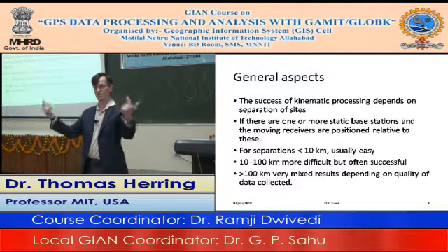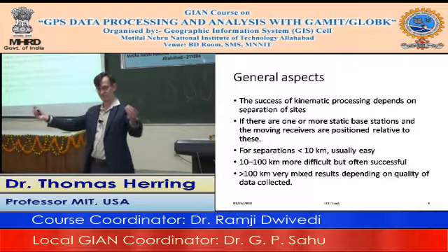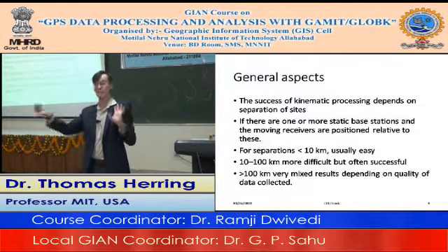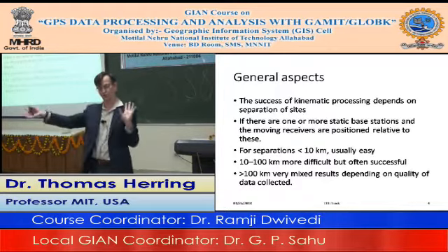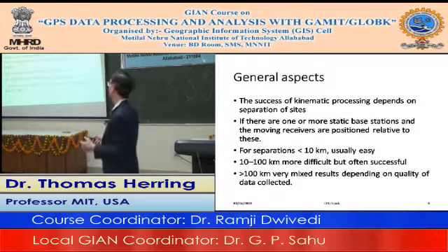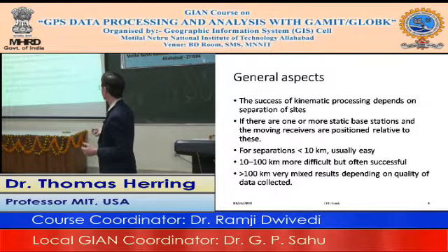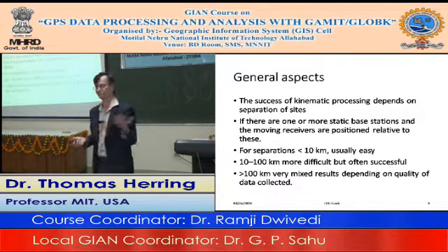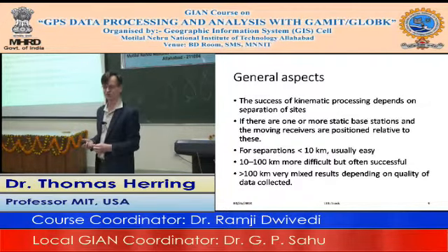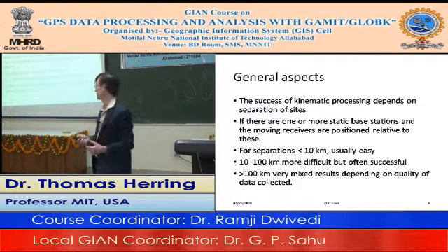So we could actually keep, when you go very far apart, you have a problem that the satellites that you can see from one receiver to another receiver are different. And so if you get too far away from your base station, you lose mutual visibility and you reduce the number of satellites. So we can do that. I must admit, for separations of less than about 10 kilometers, this Track kinematic stuff is always pretty simple. You pretty much can run it under defaults, provided the receivers are not sitting underneath trees or something like that, provided the data is reasonably good.